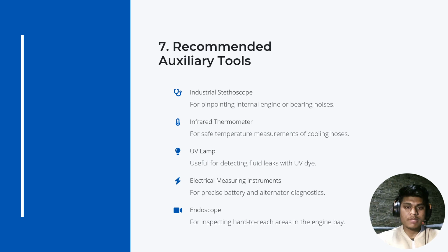To elevate the professional value of this report, I'm utilizing several specialized auxiliary tools. An industrial stethoscope is used to pinpoint internal engine or bearing noise that is not audible to the naked ear. For safety, an infrared thermometer allows me to measure the temperature of cooling hoses without physical contact. I'm also employing a UV lamp to detect potential fluid leaks via UV dye, and electrical measuring instruments for precise diagnostics of the battery and alternator output. Lastly, an endoscope is used for a detailed inspection of hard-to-reach areas within the engine bay.